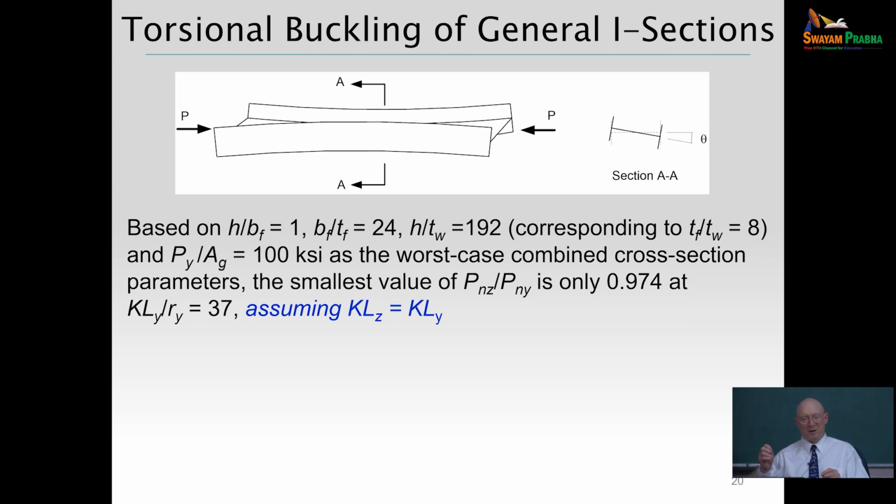Once you have a controlling capital FE, which is your elastic buckling stress, that feeds into the normalized or non-dimensional slenderness for getting your column strength, or in AISC, since we don't like Greek symbols in the U.S., we put it into the Fy over Fe in the column strength formula.